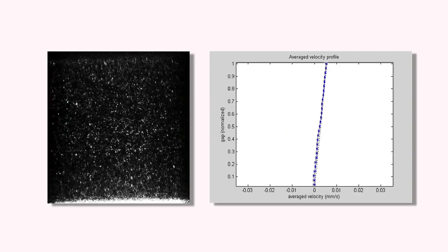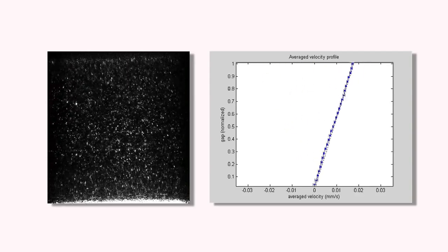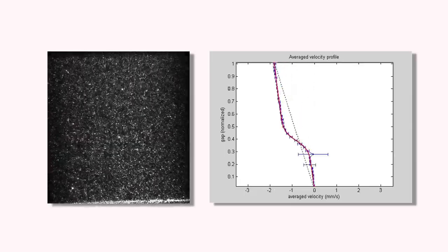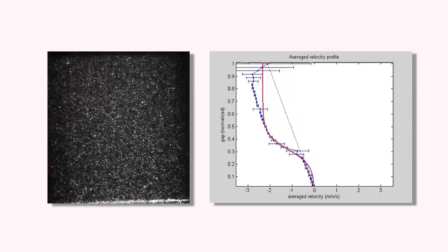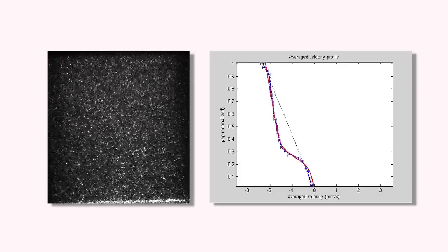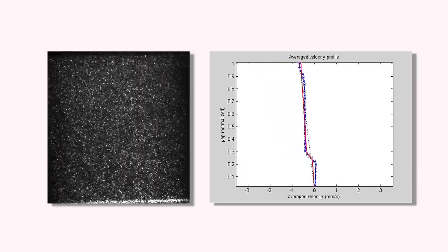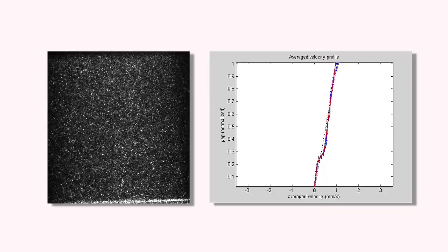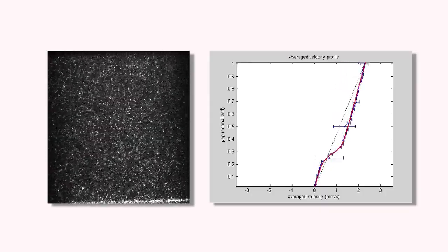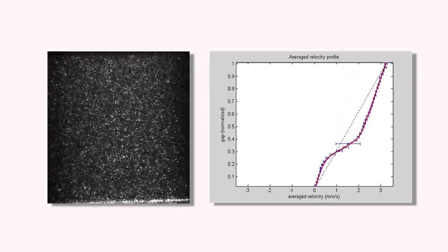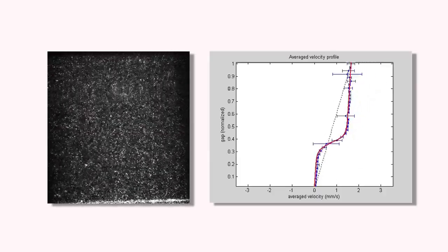As the material starts to become nonlinear and shear band, however, things become more complicated. Here's the velocity field in a large amplitude oscillation, and you can see that the fluid is moving from left to right, but in the middle of the material there's a shear band, and the position of that shear band is time dependent as we go forward.